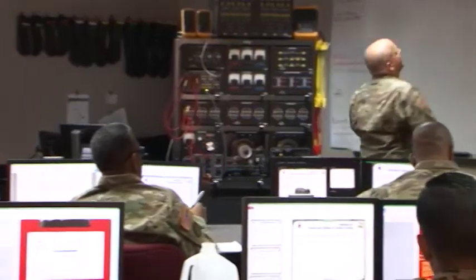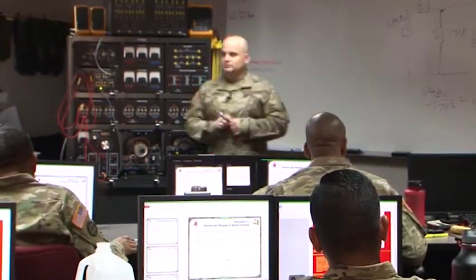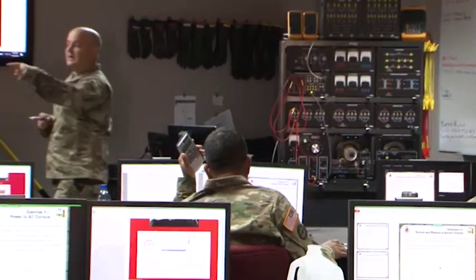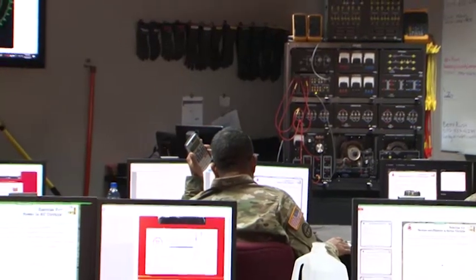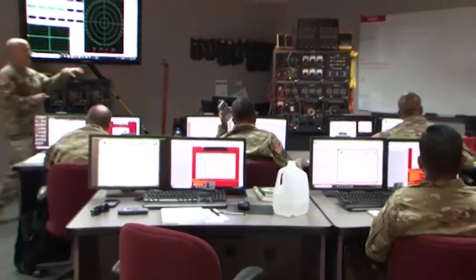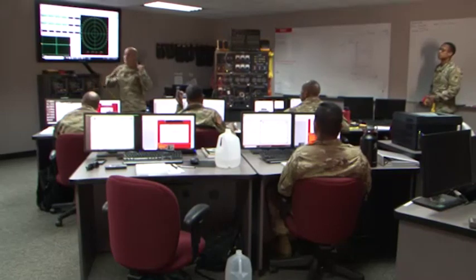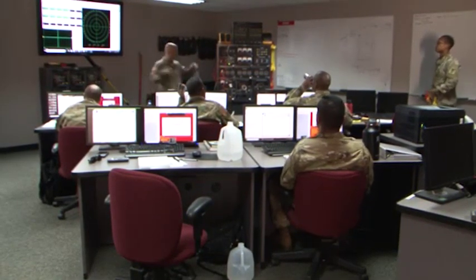What is my real power consumed in this circuit? It's the same on this. There's no reactive power. So what's the phase angle between current and voltage? There isn't one? So that means it's in phase, right? Yes. So then if we were to pop this circuit up on the oscilloscope, we should be able to see that they rise and fall, they peak, they start, they zero, same point, right? Yes. And what our meters should indicate is all this math we did. Cool.